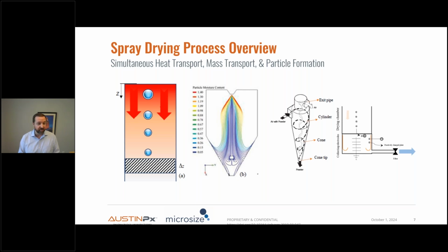And so this is a mass transport event that's happening. In addition, there's a mass transport event happening upon droplet formation and the evaporation of the solvent. And then all of these particles are flowing through to a separator, and there often are significant dependencies in these process parameters. If you view particle or droplet generation as a unit operation, and then heating and drying as a unit operation, and separating as a unit operation, optimizing one of these may impact the downstream significantly, and often compromises or optimums have to be sought.